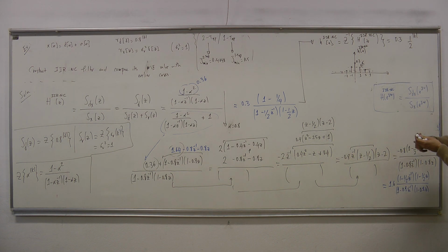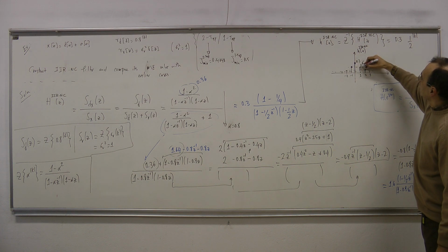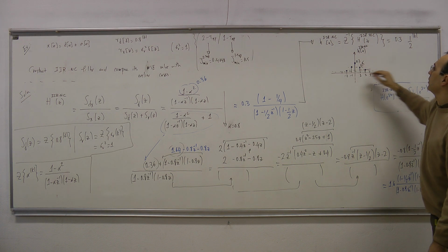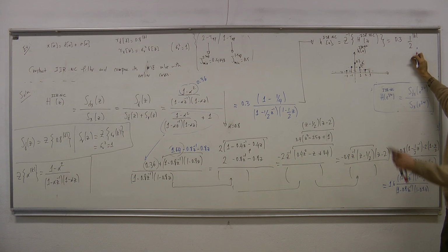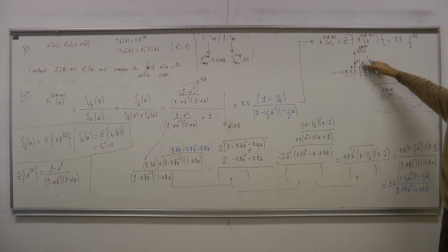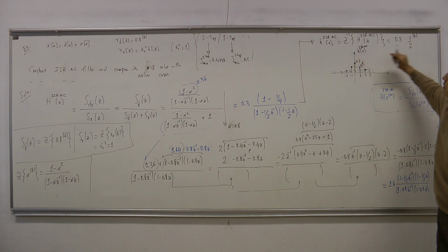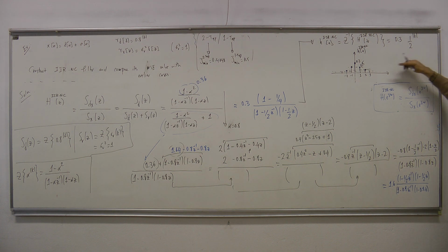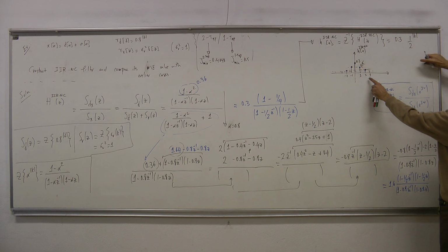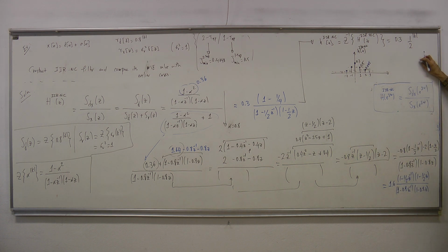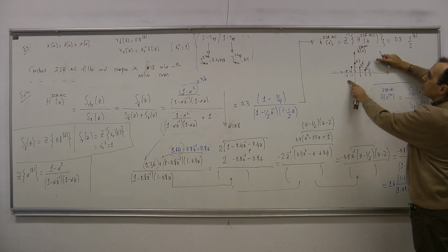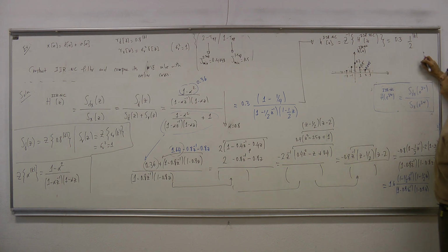Okay, so this was the thing that we were expecting, because in the processing of this, a filter is combining samples, isn't it? So to generate an estimate for the nth sample, it's processing the current sample by 0.3 in this case. Then the next sample or previous sample by 0.15 because of this convolution, and the previous sample with the same weight. Because the processes are always reversible, why should they have a different weight, isn't it? Then the second sample in the history by 0.1575, okay, by this number. Then the second sample in the future of this sample by the same weights, because processes are, as we have said, reversible. Okay, so we got this optimal filter.